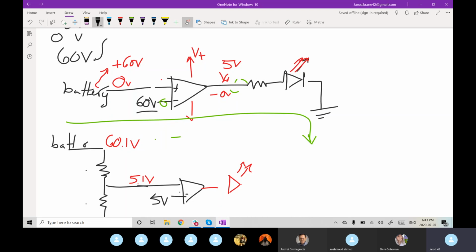So you'll be able to find a number in a datasheet saying something about it, but your open loop gain is typically, it's going to tell you it's some 100 dB, I think they refer to it. So it basically wants to take whatever your input and multiply it by this massive number, because again, our output is just our input times some gain.